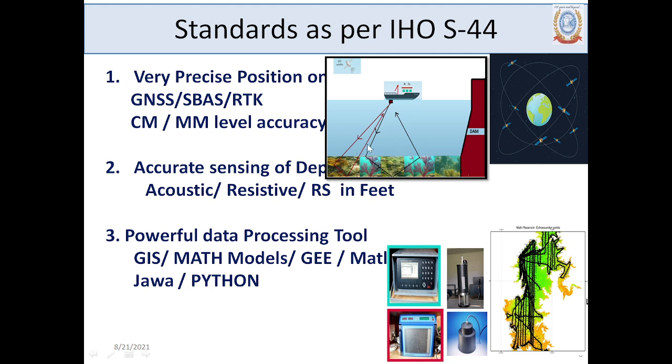This is a multiple echo, so this is read as a larger depth actually. So the sound goes here, takes a reflection, takes back, and comes back. So what happens is this amount of travel time is assumed by my sensor as a deep zone. So it measures that this particular reading is going to be, say for example, 20 meters compared to this reading is going to be 10 meters. So at this point I will be reading it as 20 meters. So 12 meters of error I am making.